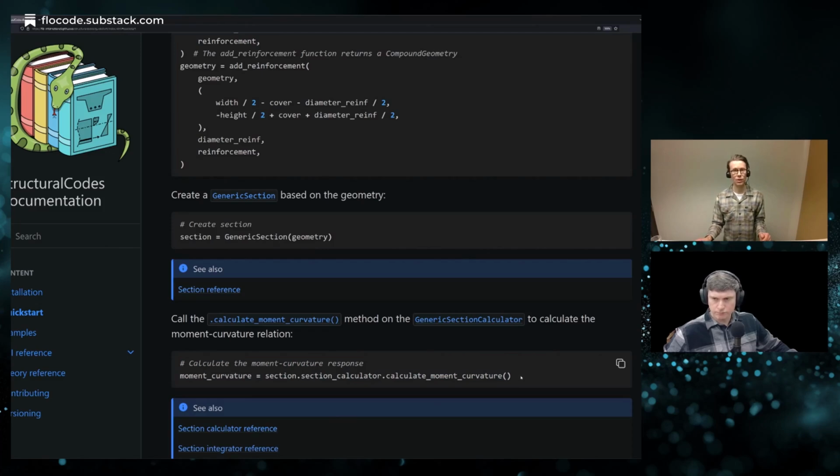When we switch to Visual Studio Code now, I will demonstrate what this does. We've defined the perimeter of the cross section, which is a rectangular cross section. We've defined two points which represent our reinforcement, and then this final generic section function literally creates that 2D full section and combines everything together. So the geometry is already ready from this stage, but then we wrap it with some methods to work on it as well. Cool. That's awesome.